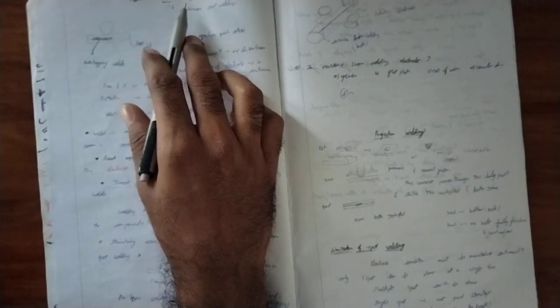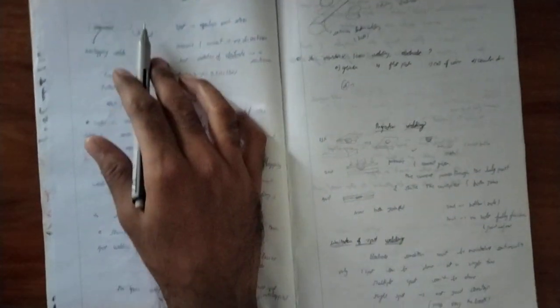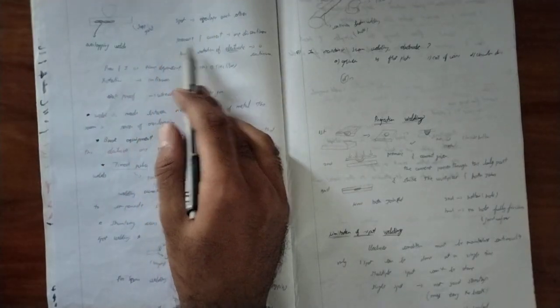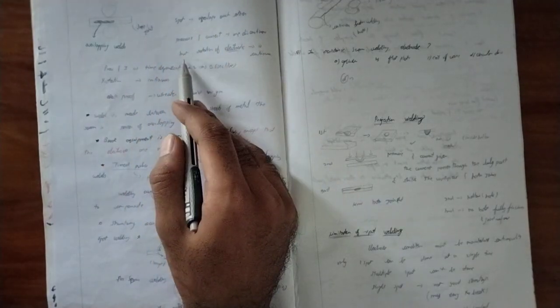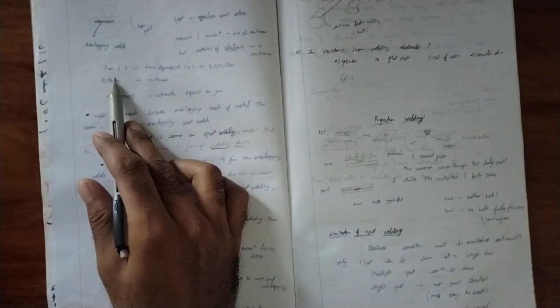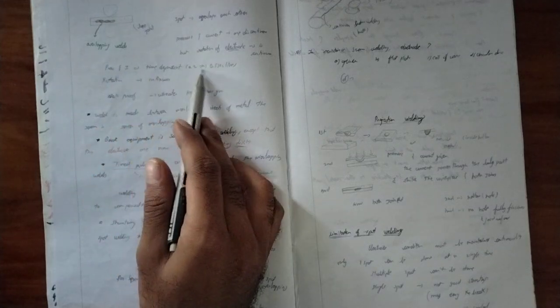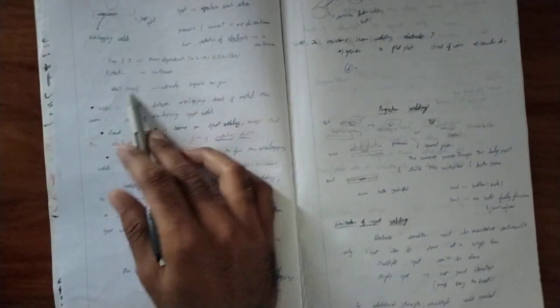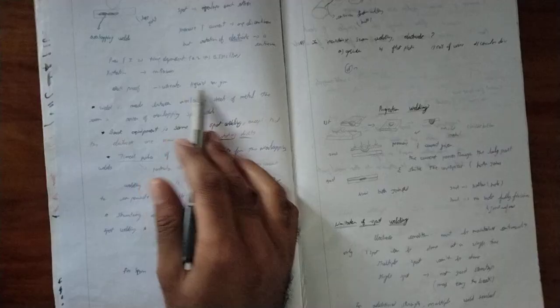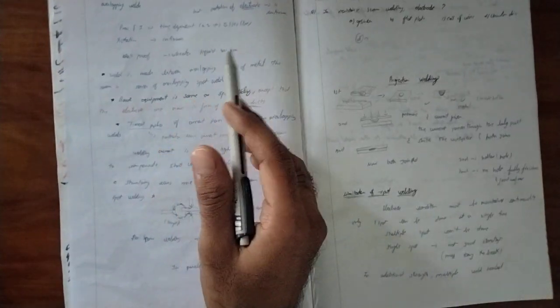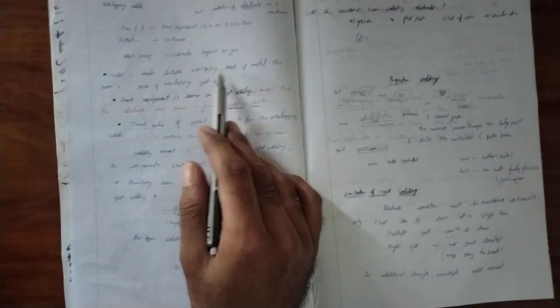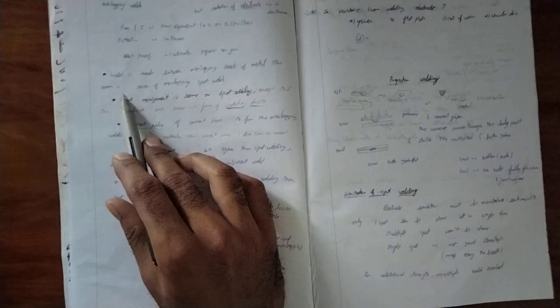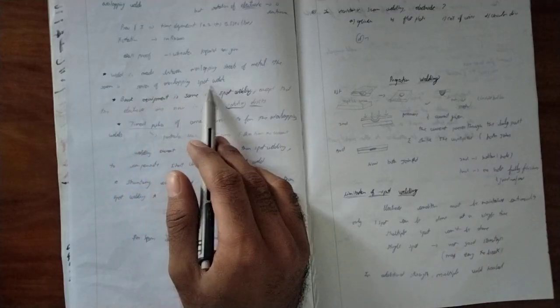So you can see resistance seam welding: continuous spot welding where the spots overlap each other. Pressure and current are discontinuous, and the rotation of the electrode is continuous. Pressure and current are time independent. Time will be changing, but the rotation is continuous. It is leak proof, especially for liquids and gases, so we use it for cylinders, and the weld is made between overlapping sheets of metal. The seam is a series of overlapping spot welds.